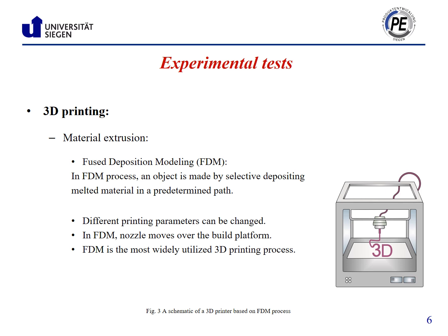Fused deposition modeling, or FDM, is a technology in the family of material extrusion. In this technique, the melt extrusion method is used to deposit filament of thermoplastic according to a specific pattern. In detail, the nozzle moves over the build platform to produce the parts layer by layer directly from a digital model.